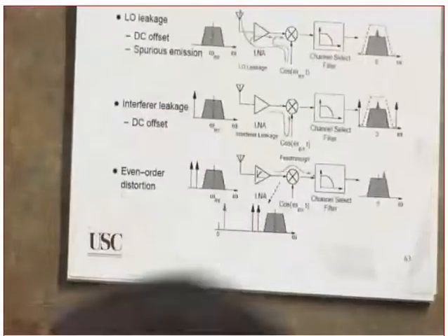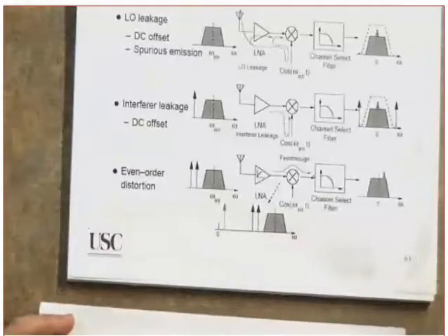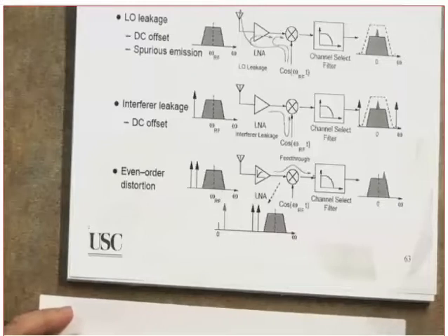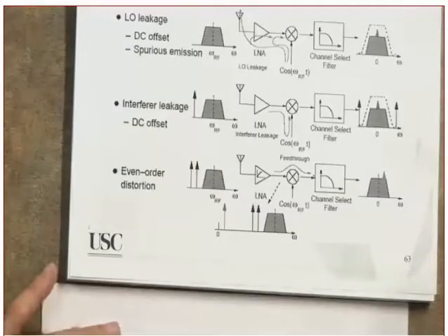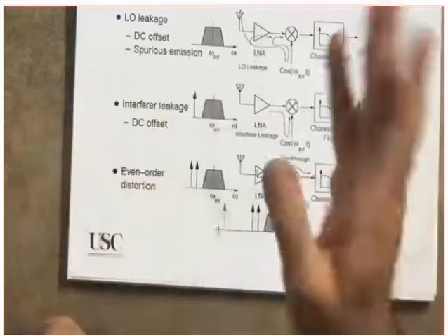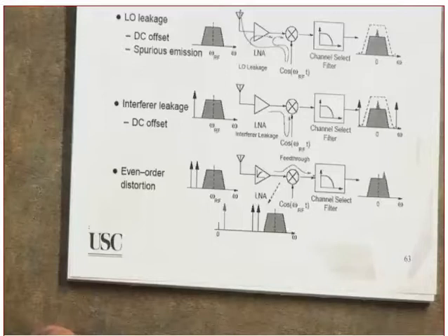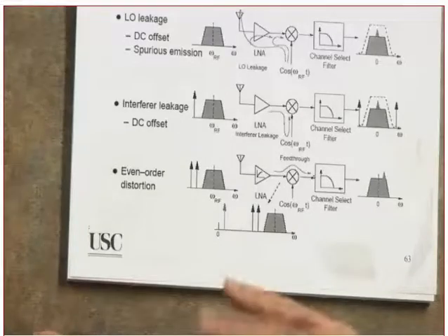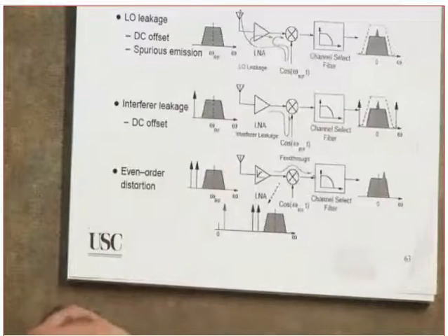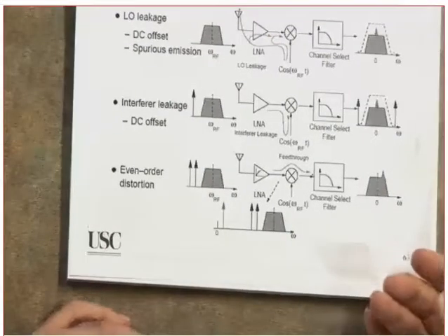Yes. For the superheterodyne receiver, in the last mixing stage, are we going to suffer from the LO leakage? A little bit. But that is, by the way, you always suffer from what? The leakage. Are you following? In the superheterodyne, but not at the first stages. Which one has more filters along the chain? The superheterodyne. The more filters you go through, it means you are getting rid of many what? Interferers along the way. Did you get this or not? Whereas in here, it's just that filter and the baseband. Clear? Clear?